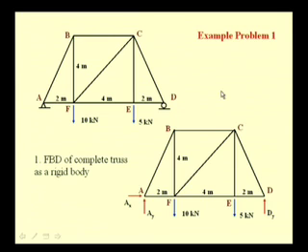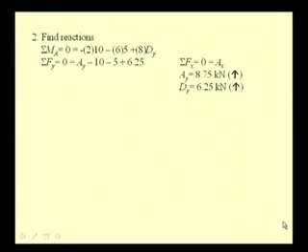And since we have only 3 unknowns, and from 2 force summation equations and 1 moment summation equation, the 3 unknowns can be determined. So, we have taken in this case the moment summation about point A, which gives the value of Dy, and the 2 force summation equations, that is sigma Fy and sigma Fx, give Ay and Ax.